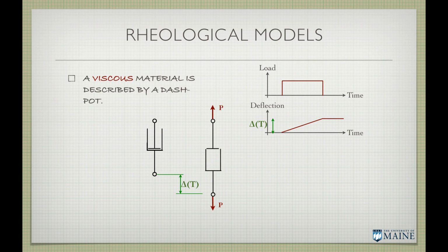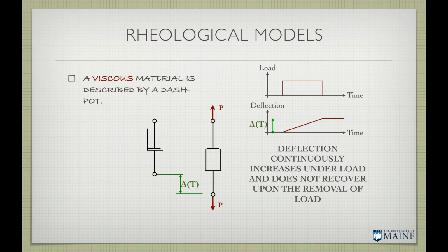So that deflection is a function of time. In this case, it's a linear function. So deflection continuously increases under load and does not recover upon the removal of load.